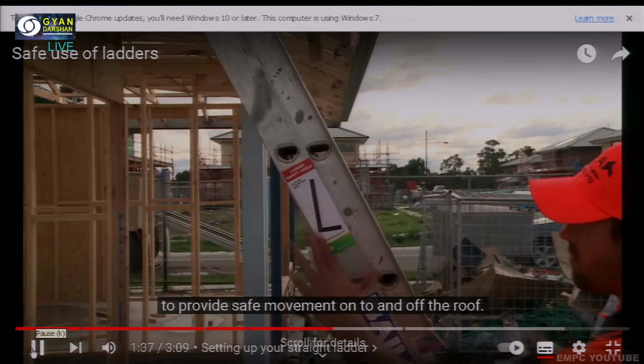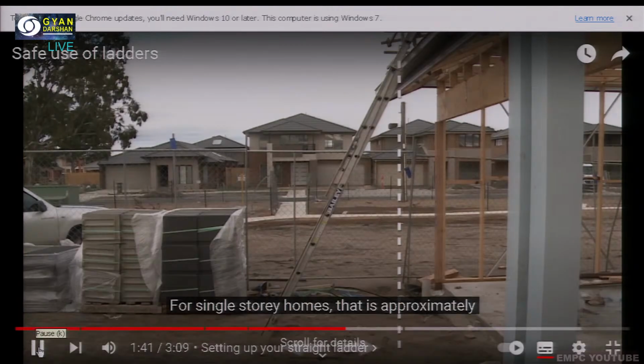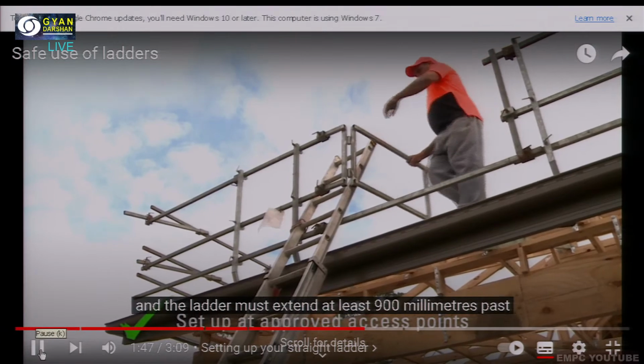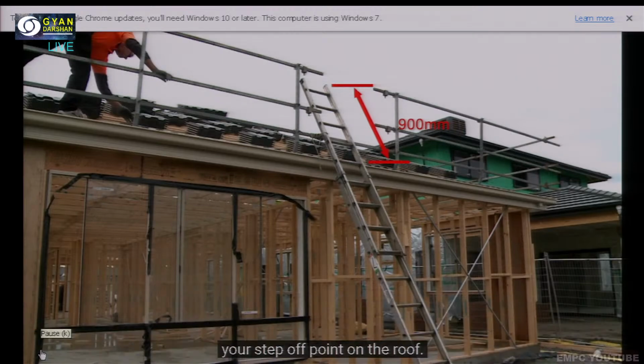Again, we saw that there is a 1:4 ratio while setting up a ladder, or 75 centimeters as we saw. The extension of the ladder above the point of vertical support is 900 millimeters according to the code that is shown here, but we usually follow 1 meter.